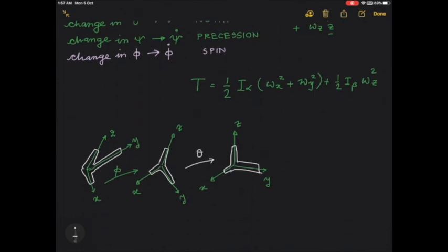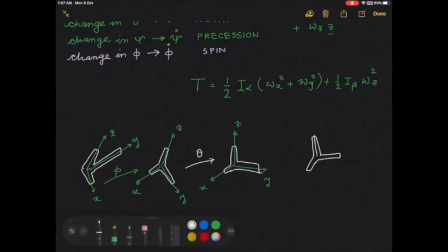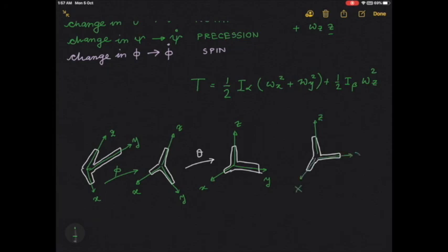And then now I can do the psi rotation, which will orient my x-axis differently. So x and y will become like this, x will become like this, z remains as it is. So that's the rotation about z, which is now along the body z axis, and my x and y also become the body x and body y axis. So you see, these three angles that we looked at are nothing but the Euler angles that we have discussed many times now.